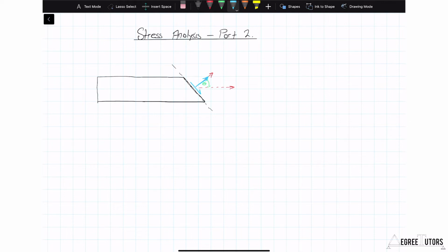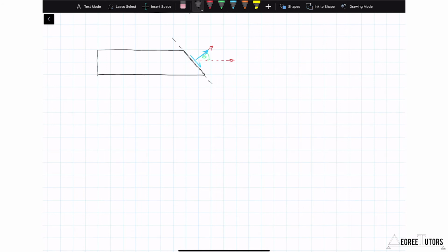All right, so let's start off by making a couple of statements. We're going to first talk briefly about this concept of plane stress, because everything we're going to look at now is going to be based on a condition of plane stress. We're assuming our beam here is in a state of plane stress. We're going to call this a refinement of our problem. We're essentially defining an assumption here, which is what we do quite commonly in engineering, and certainly when we're deriving things: we're going to reduce the problem to a slightly easier to manage thing.